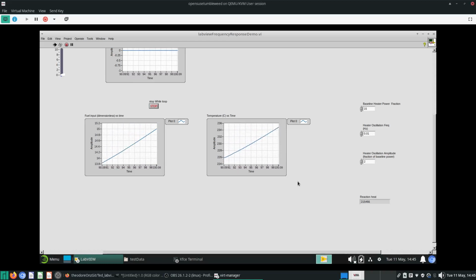Okay, so at least for us, if we assume that the system is linear within the interval that we are testing, we can actually, instead of using a clean sine wave as the input, use multiple superimposed sine waves as the input.